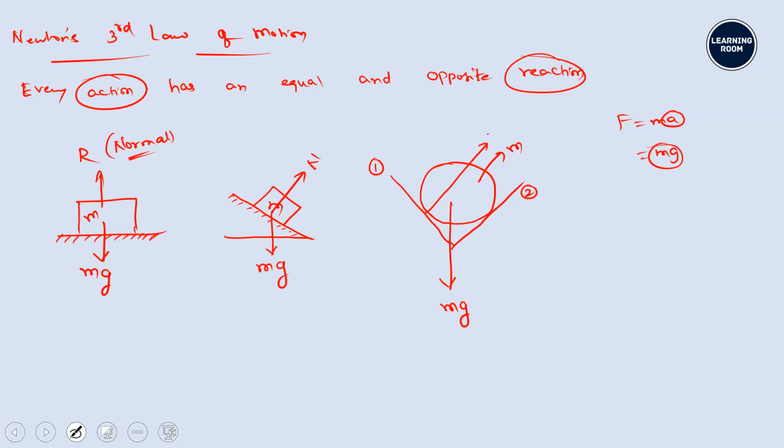So this will exert a normal force perpendicular to itself. You can call that N1. Then there will be a normal force acting perpendicular here also. You will call this N2. Here N1 might be equal to N2 or they might not be equal. We don't know unless we have the mathematical parameters and I need to know different values associated with it. Again, I repeat, here the context is to explain the different kinds of reactions.